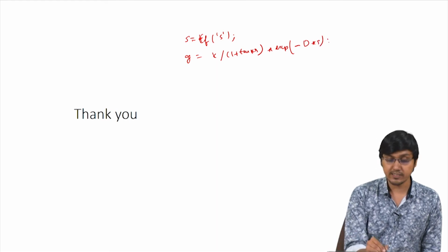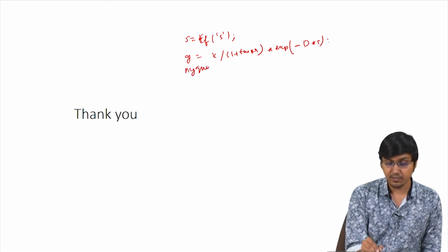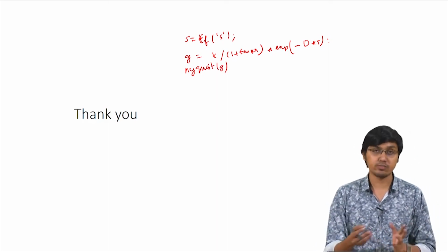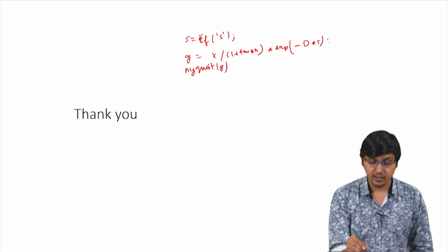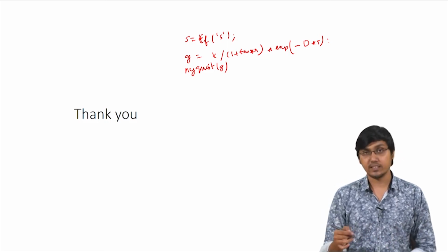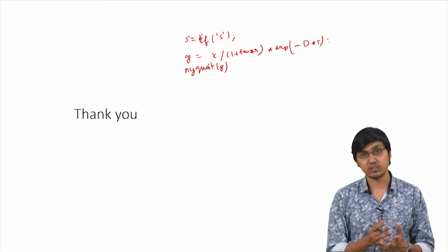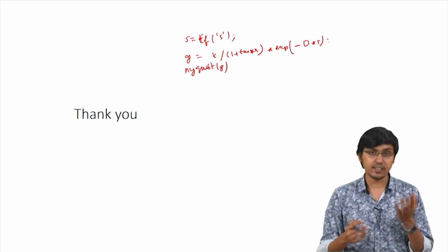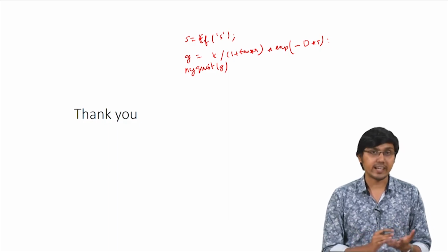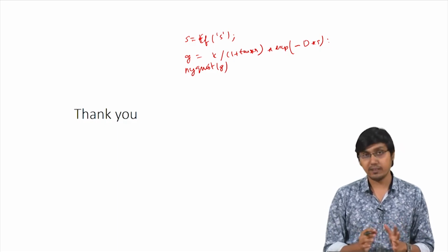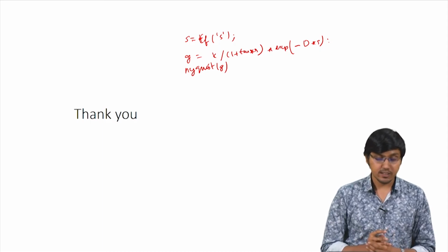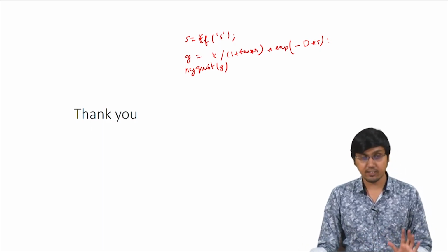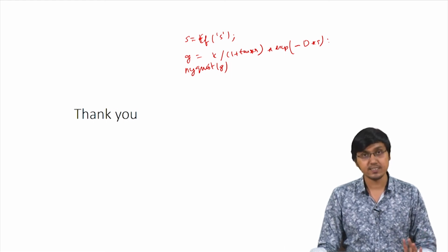If you do this and then put the Nyquist here, you can plot this Nyquist graph, substitute various values of K, tau and d, and see what actually happens when the system goes unstable, and what the effects of dead time on stability are. It will be interesting for you to try and learn these yourself, and that will make things more interesting. So, with this we have come to the end of the lecture on Nyquist stability analysis. Thank you.